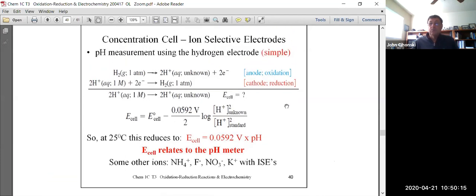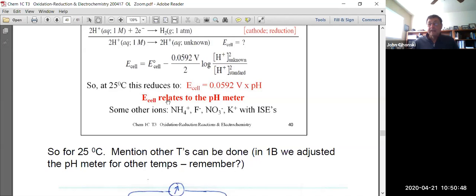Okay, now, what these are called are ion selective electrodes. In other words, it doesn't matter what else is in solution. Whenever we do pH, and there is other stuff in there, the electrode is constructed not with an actual hydrogen electrode, so that the only thing we are sensing is the proton concentration, okay? That allows us to be very selective in what we monitor and measure.